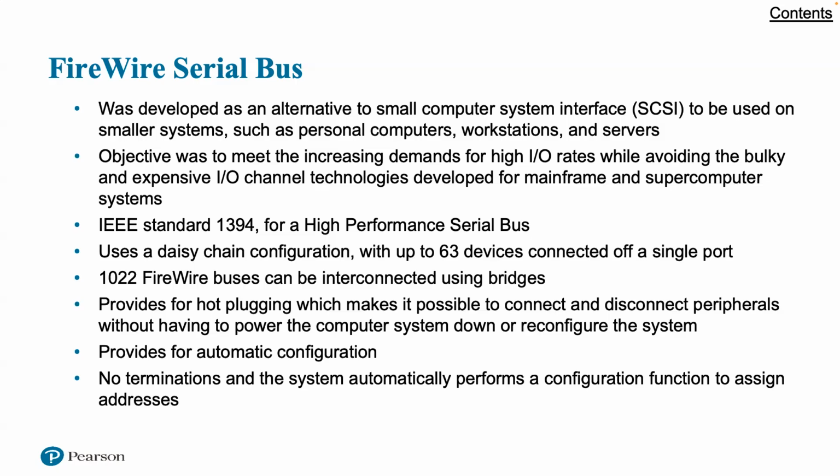Also, FireWire provides for automatic configuration. It is not necessary to manually set device IDs or be concerned with the relative position of devices. With FireWire, there are no terminations, and the system automatically performs a configuration function to assign addresses. A FireWire bus need not be a strict daisy chain; rather, a tree structure configuration is possible.